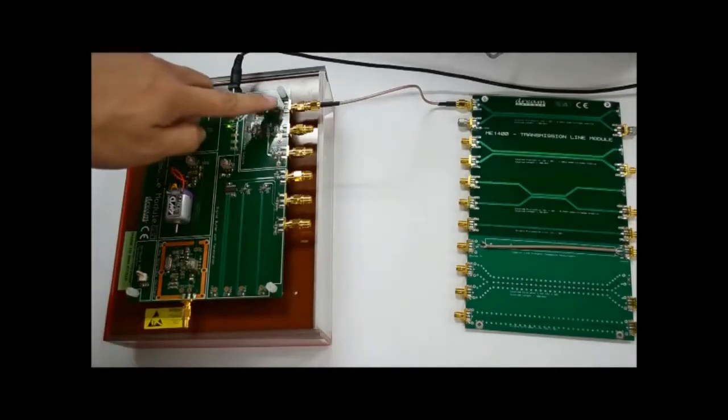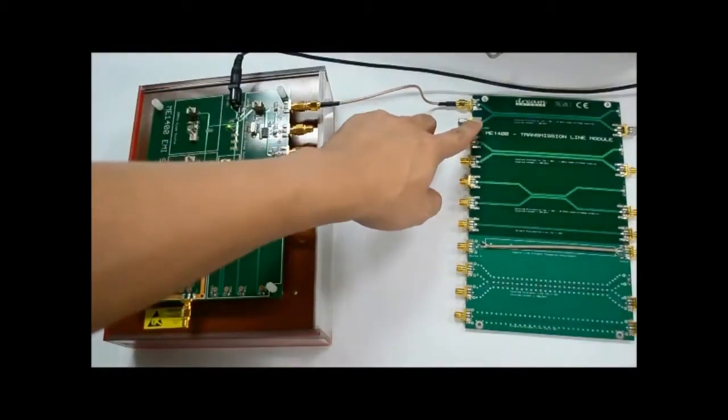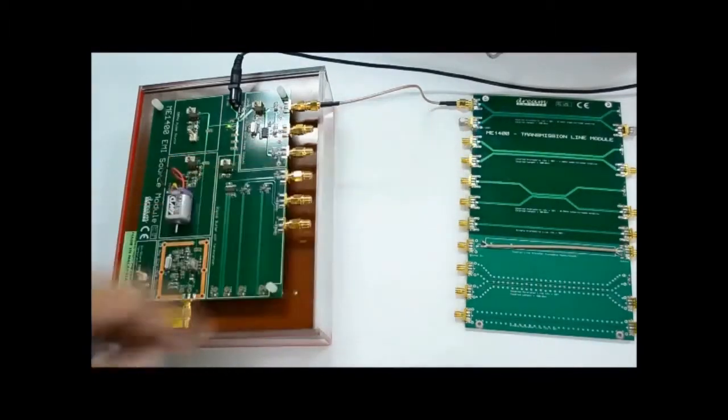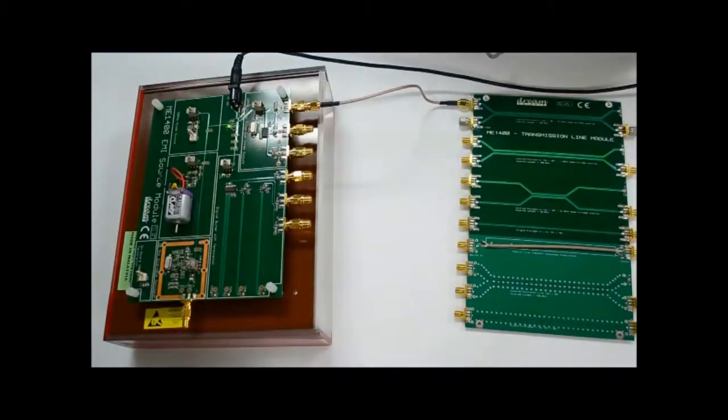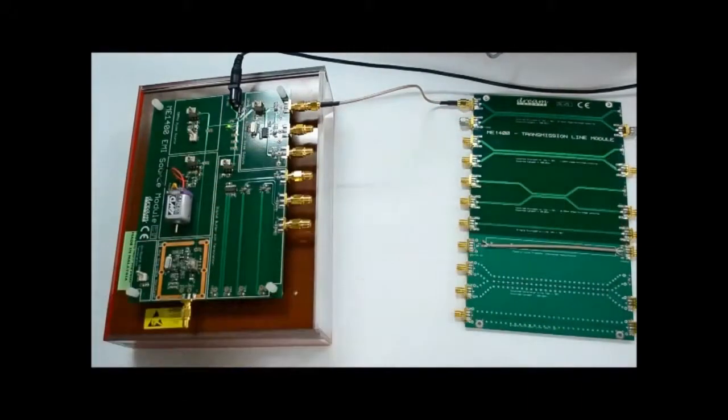The high-speed pulse on the EMI source module is connected to the active trace of the coupled microstrip line. The microstrip lines have an edge-to-edge spacing of 0.56 mm and a coupled length of 100 mm. Both ends of the induced lines are terminated with a 50 ohm SMA connector.